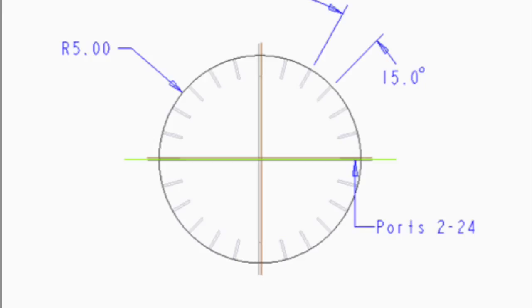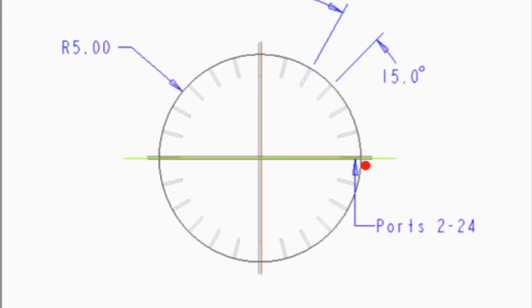A LabVIEW virtual interface was used to collect this pressure data in addition to free stream velocity at the test section inlet. An additional port connected to measure stagnation pressure in the wind tunnel was used as a reference to identify the port in the cylinder that was at the stagnation point. To trip the boundary layer, a tripwire was secured across the length of the cylinder with aluminum tape directly below the port that faced towards the flow direction, as shown by the red dot.